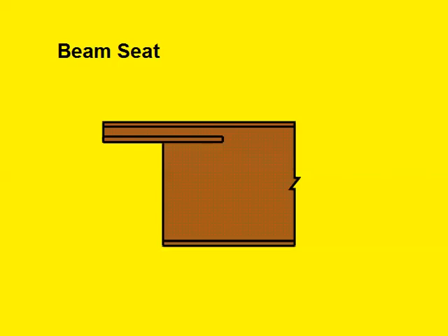But this creates a little bit of a structural problem, doesn't it? Because you don't have much left for shear at that point, and you notice the stiffener going back. That's so that we don't overstress the web as well, and you have to take the bending here as well. So it's a simple design procedure, but you better remember to do it.